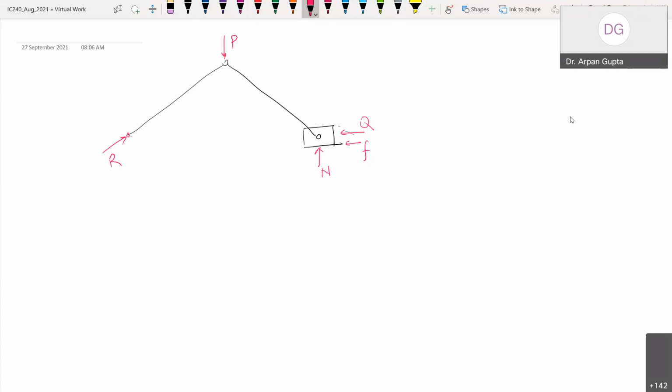Right. So this is the same stone crushing machine or mechanism that we have seen in the last class, but now we are considering it with friction. So this is the extra force small f, and now we are assuming that it is on the verge of sliding, right? So we want to calculate the maximum load P for which it is just about to slide. So in that case, your F will be equal to mu times the normal reaction N. And if you see the geometry, this is L, and this angle was theta.